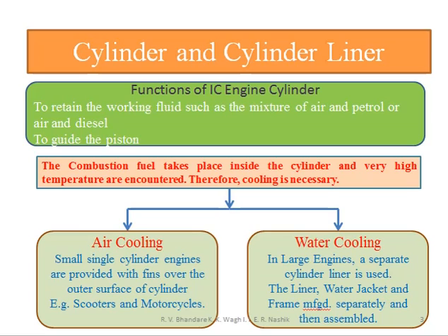As we know, the function of the cylinder and cylinder liner is to retain the working fluid, such as a mixture of air and petrol in a petrol engine and air and diesel in a diesel engine. It will also guide the piston under the gas force.